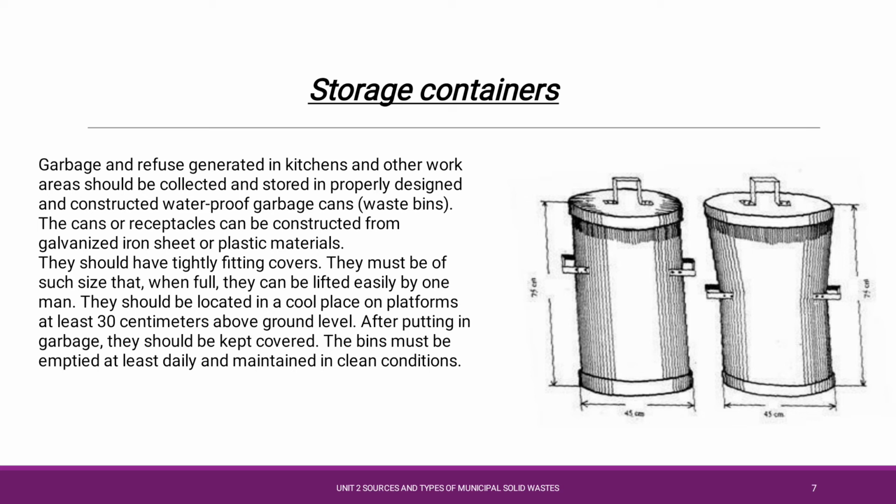So these containers must require one or two crew members to carry and handle the waste, that is, for loading and unloading of the waste. This container should be placed at a proper distance on a proper platform which is at least 30 centimeters above the ground level, with a proper interval of duration.